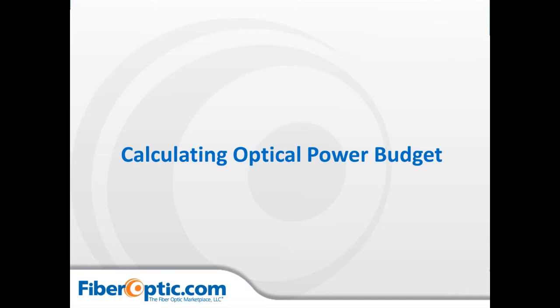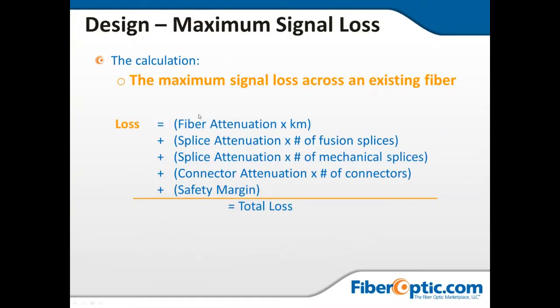I'm not going to go into great detail, but suffice it to say that every little bit of light that is lost through the transmission, through our physical plant, our cables, our connectors, our splices, at 100 gigabits or even more, has to be pretty much accounted for. And too much back reflection heading back to a transmitter can affect, say, the quality of a picture for a cable TV company, or could even begin to damage and affect the outbound signal or affect a very expensive laser amplifier. So as we pull out the stops, we've got to get more and more accuracy and minimum loss. Now here's a simple design.